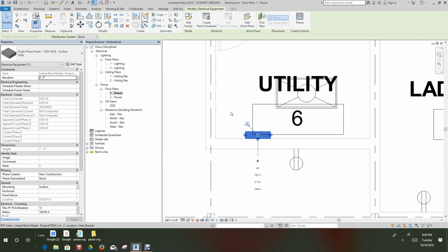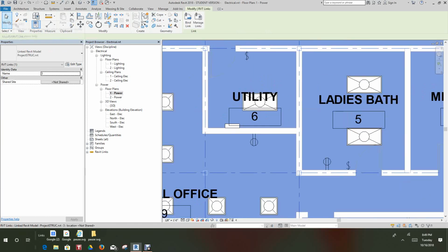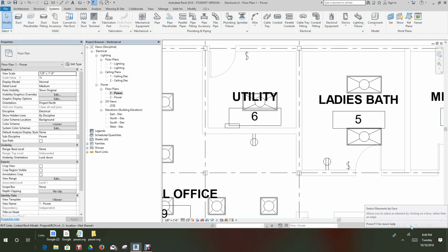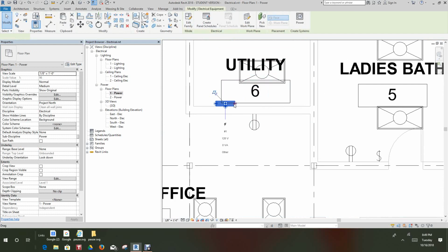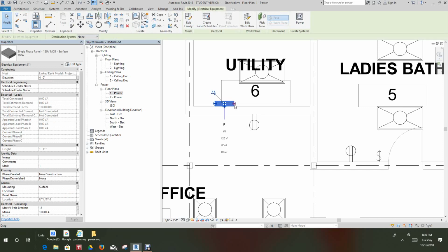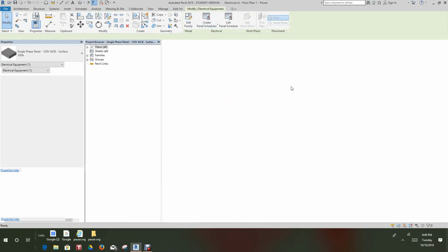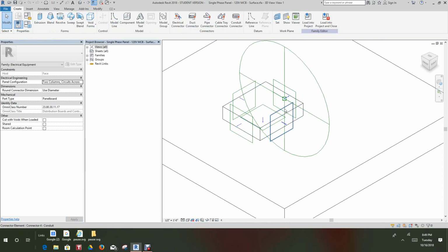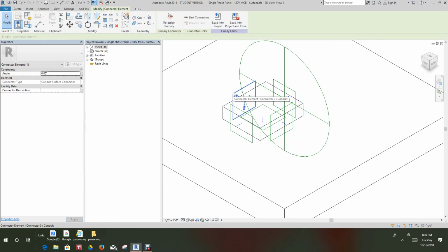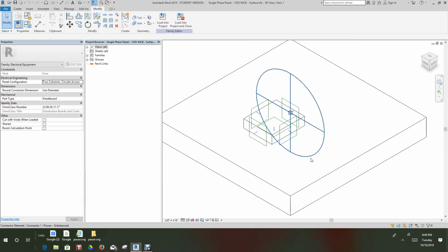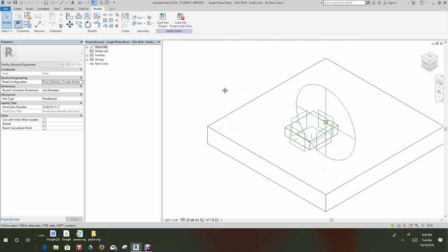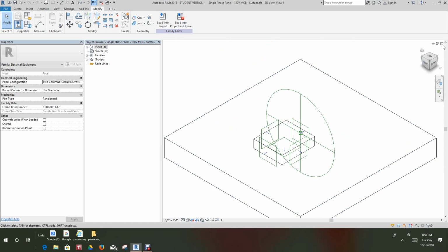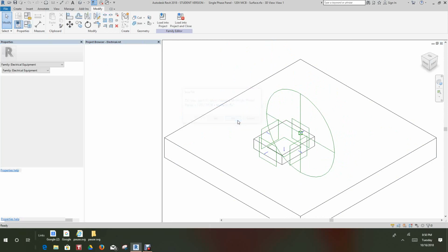So what I want to do is open this family here and hit modify again. And I'm going to turn this off so I can stop selecting the face so much. There, oh, still doing it. So let's open this panel family up, or they can just go edit family. So now, as you can see, there are the connectors for the conduit. These guys here. And this is the connector for the power circuit up here. It's all a face-based family. We know how that works because we worked on families in the past. So now let's close this down. We don't want to save it.